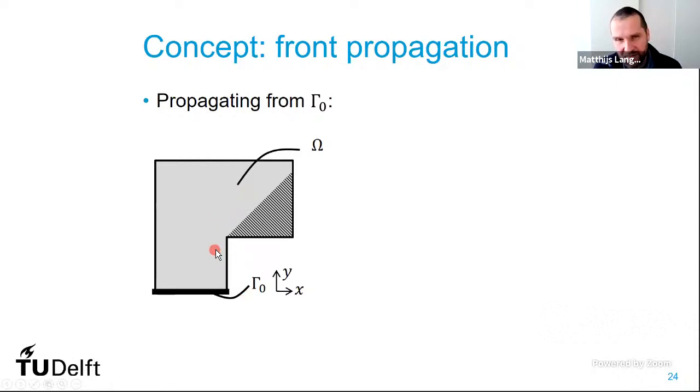And what we would like is that this field can essentially identify what is the printable region, or also identify what is the overhanging region that cannot be printed. And in order to do such a front propagation, there's this Eikonal equation that governs it, which says that the norm of the gradient of the time field is equal to 1 divided by the velocity function at that point.